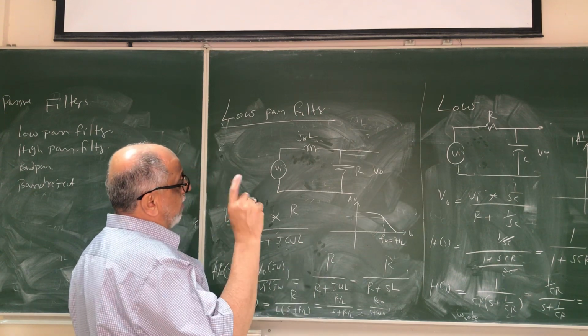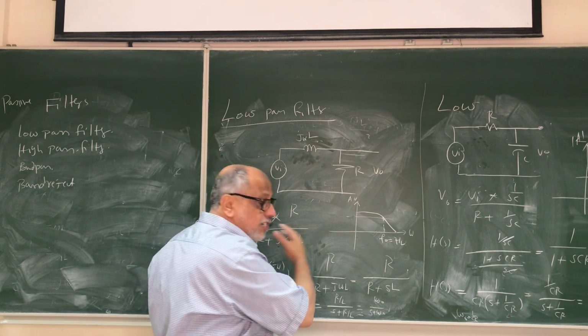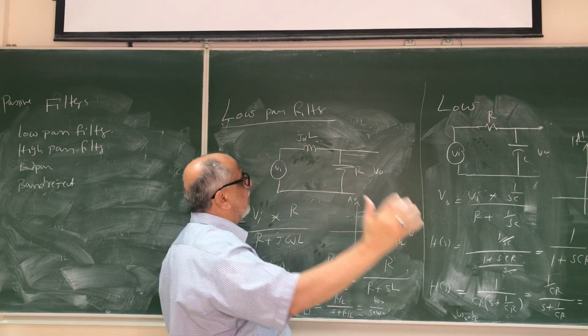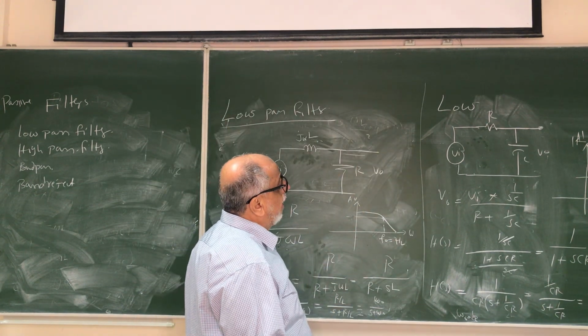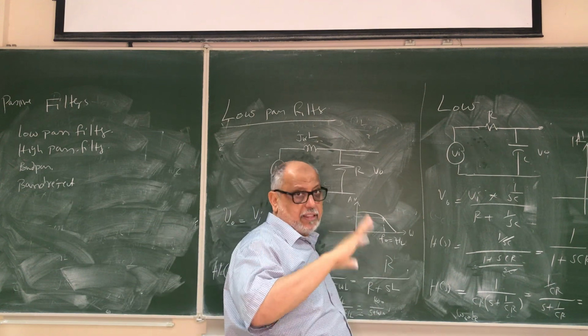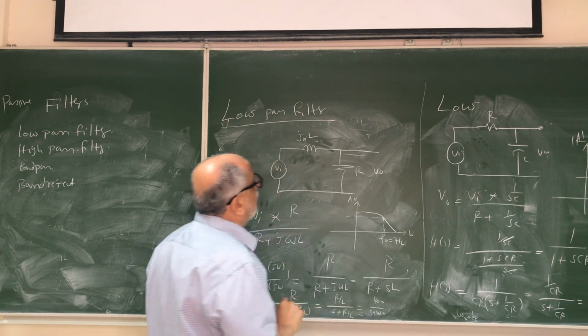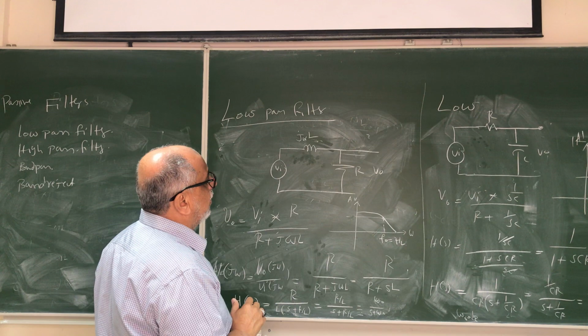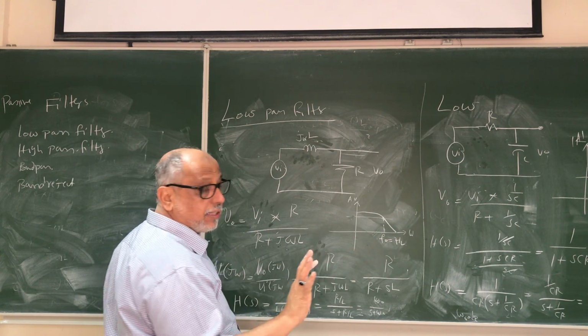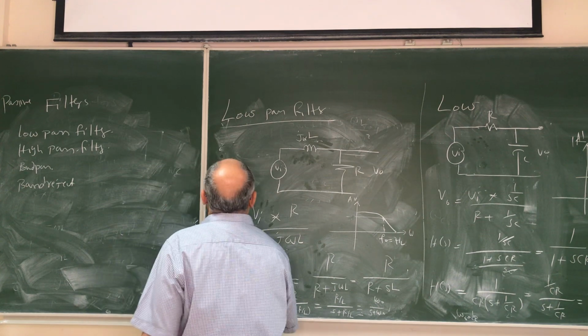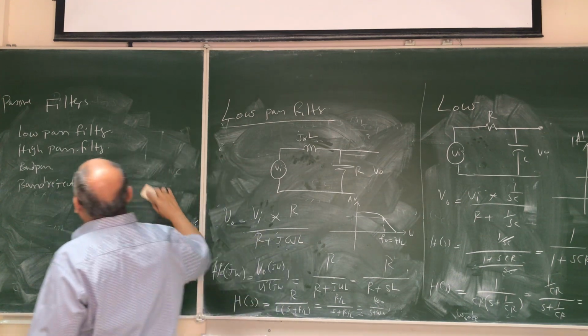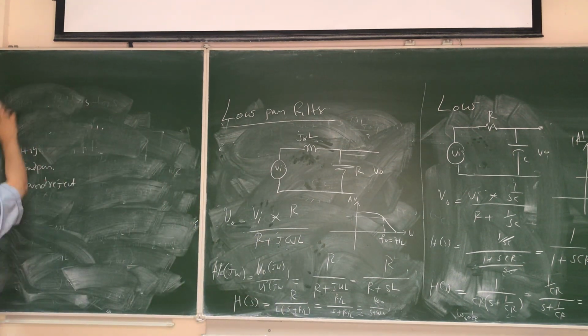Luckily, they have good things, that the frequency range is very large, so you can go mega, giga. There is no problem. However, when you use active filters, there is a limitation. Okay, so we cannot just go in any range of frequencies. We are restricted by the integrated circuit frequency response of the op-amps in fact.